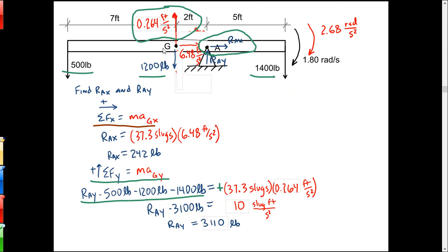And once you've got that diagram, I don't care whether it's rotating or not anymore. All I'm doing is analyzing the diagram. So I can compartmentalize everything, and I just do F equals MA, put the static stuff on the left, dynamic stuff on the right, get my proper signs on everything, and everything will come out. Okay, so that's how I approach this one.